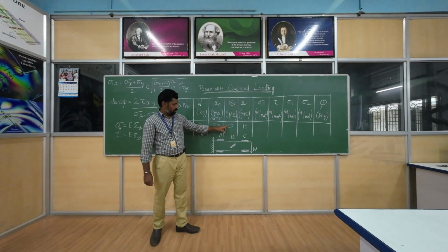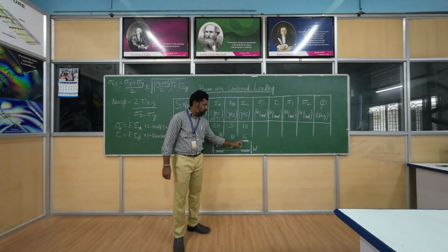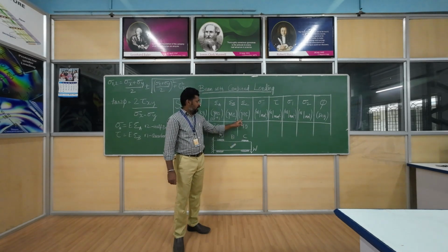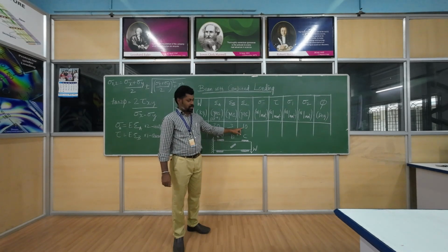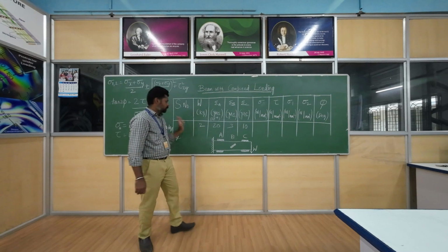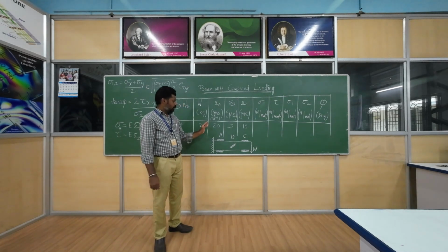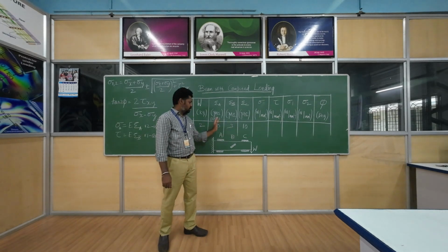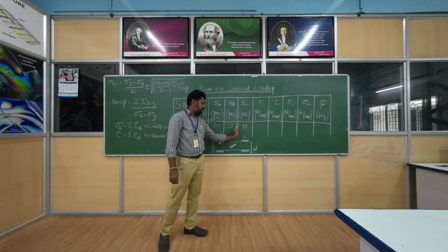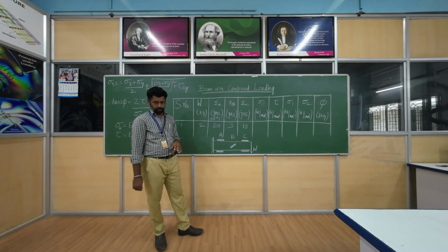So we get a strain of around 3 microstrain. Now go to section C. Section C, again, has two strain gauges. We get a strain of 10 microstrain due to the applied load of 2 kg. So now we have noted the three corresponding strains, that is, the strain at A, the strain at B and the strain at C for the given load of 2 kg.